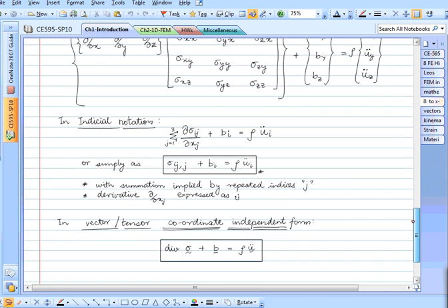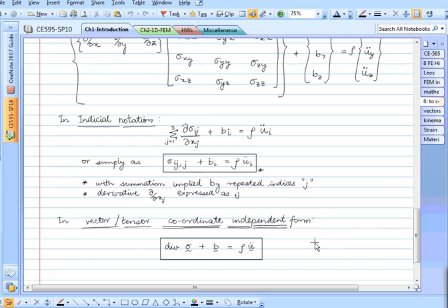All right, so this was one notation, and in yet another notation, we write this quantity as a divergence of stress, where stress is a tensor. And another note about things, I'm going to denote tensors with an under tilde and vectors with an underline. Okay, so this equation right here can be expressed in a coordinate free form. What does that mean? Somebody might say that my xyz are here. Somebody else might come along and say that, well, my xyz are here and oriented in some other direction.